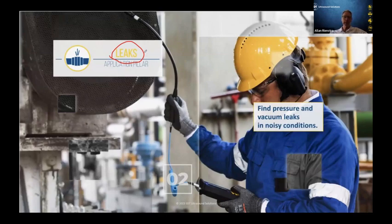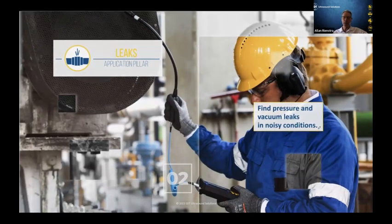Well, when things leak from a high pressure to a low pressure, it produces turbulent flow. And remember, turbulence is one of our three letters in FIT. So we can find pressure leaks and vacuum leaks. And what's key here is we can find them in noisy conditions. The background noise from our plants isn't a problem because our ultrasound detector is only tuned to 40 kilohertz. And those noisy things that we hear are down in our level of hearing, so ultrasound produces a filter to block them out.